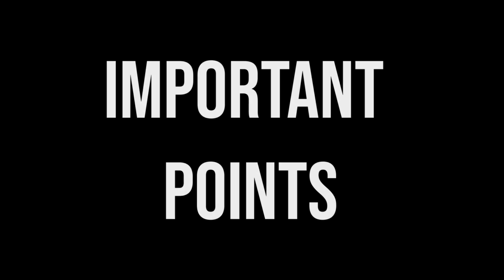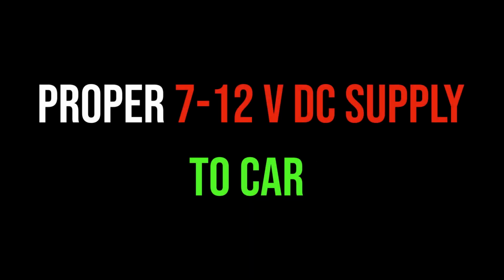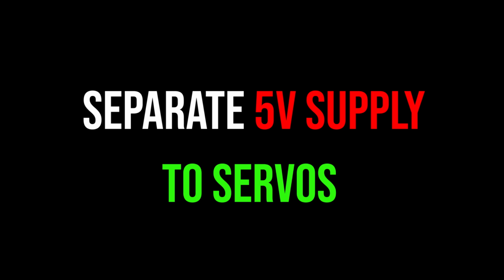We need to remember following points. We need to provide proper power supply to this car. Make sure to provide separate 5V power supply to servos.